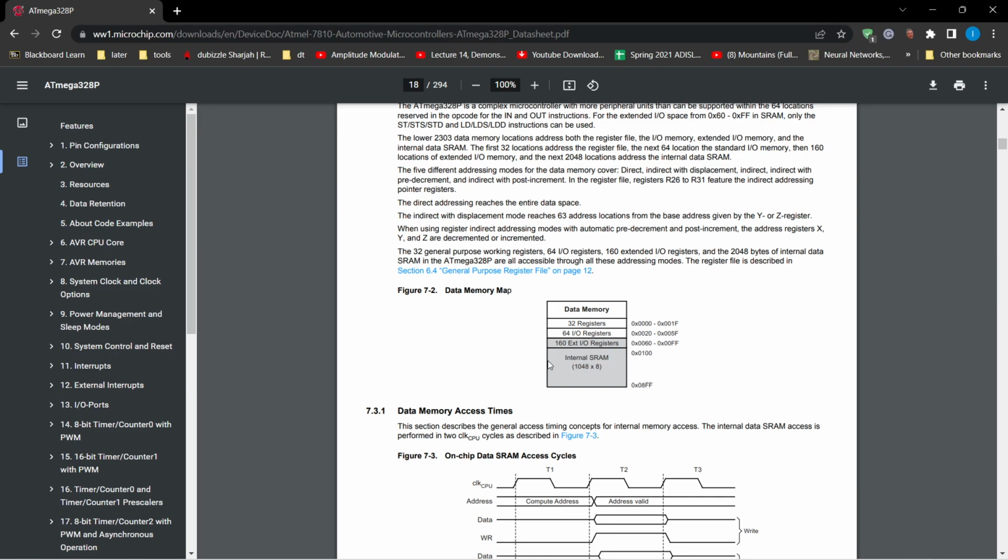Normally the stack is supposed to be at the highest value, the farthest from the data region. Normally our variables, global variables, are going to be stored in the RAM. In order to avoid any kind of stack overflow, the stack is set to the highest value.